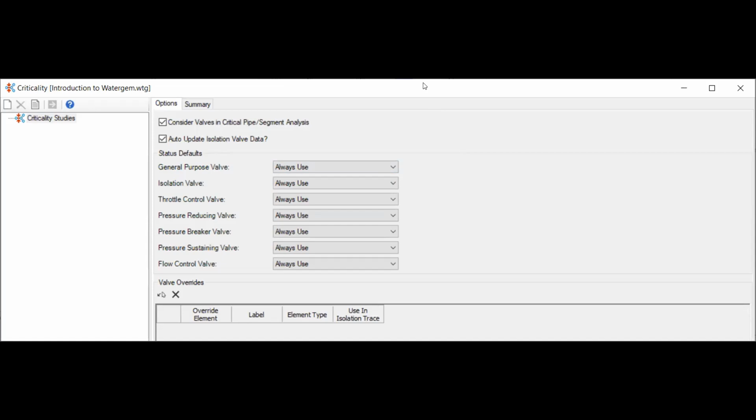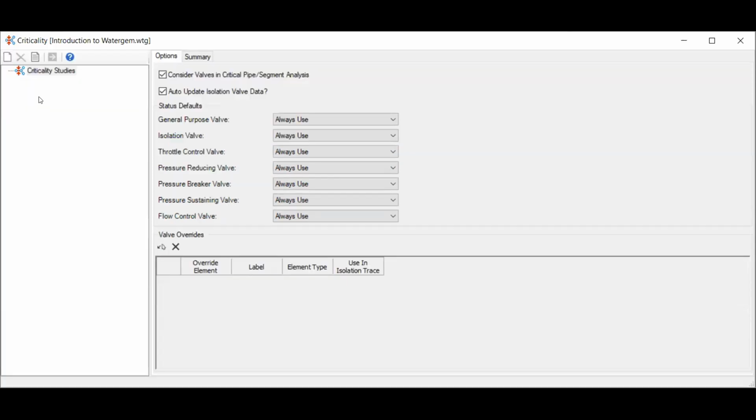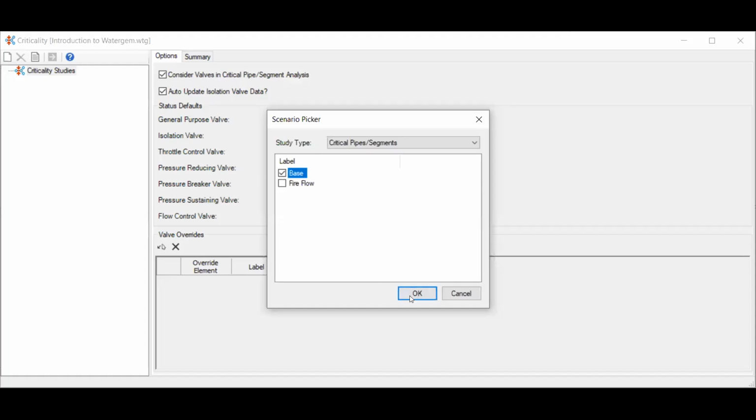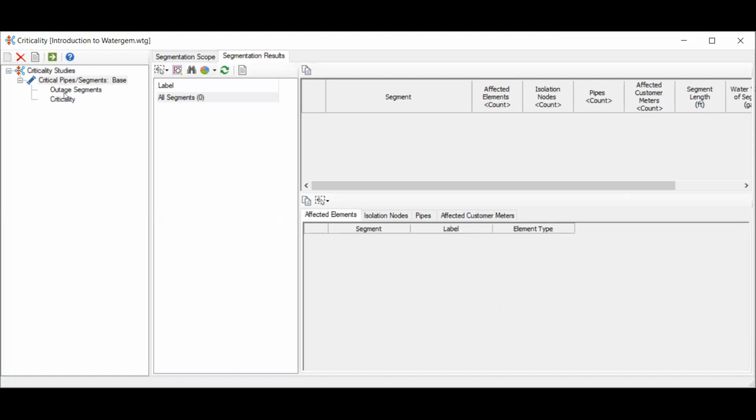So before checking the criticality of this water supply network, I will create a study for it for a base flow. You can do it for different types of scenarios. In some scenarios you may have a pump, or some extension of different types of pipes for a different area, while in some scenarios you will have a fire flow node.